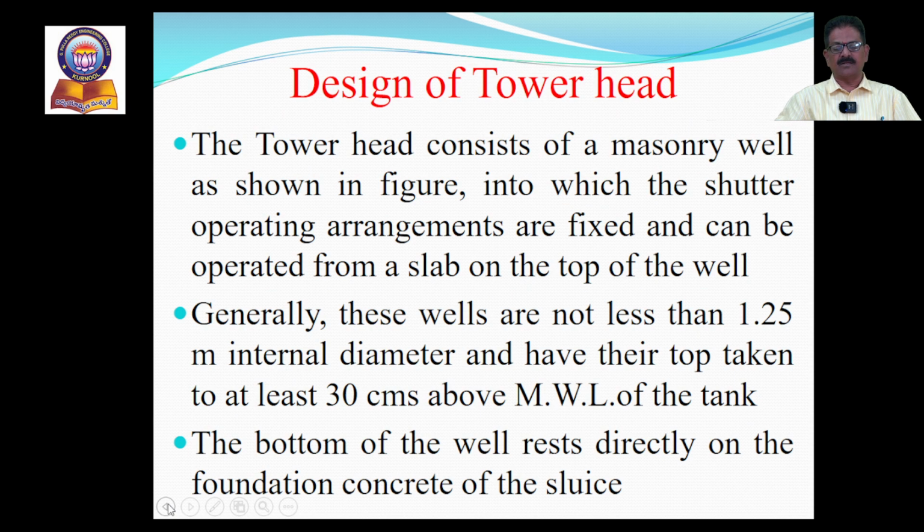Generally, these wells are not less than 1.25 meter internal diameter. That is the size of the tower. It is circular in shape as a well. Its internal diameter should be at least 1.25 meters. Also, the top should be taken at least 30 centimeters, that is 1 foot, above the maximum water level of the tank. Of course, the bottom of the well rests directly on the foundation concrete of the sluice.